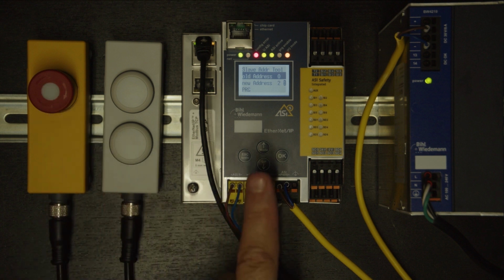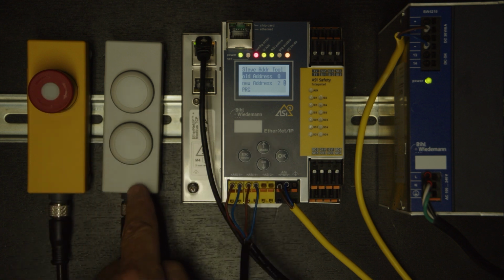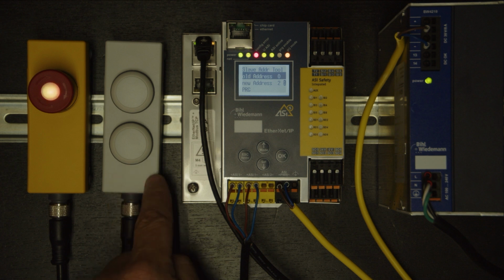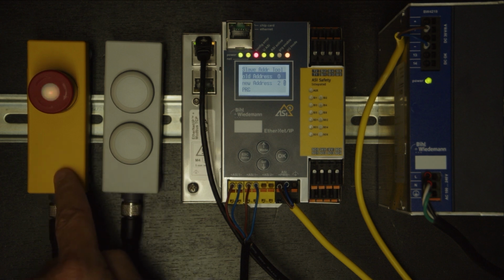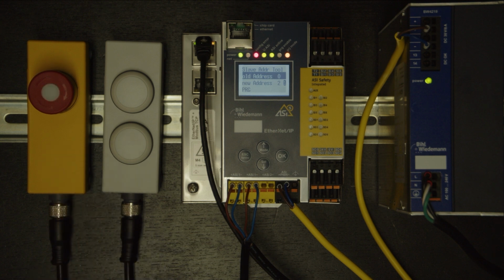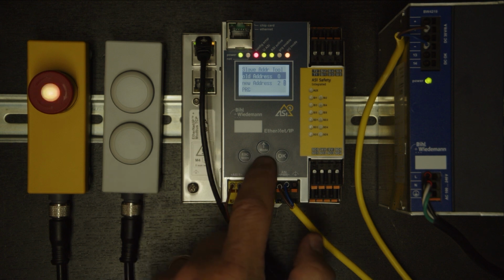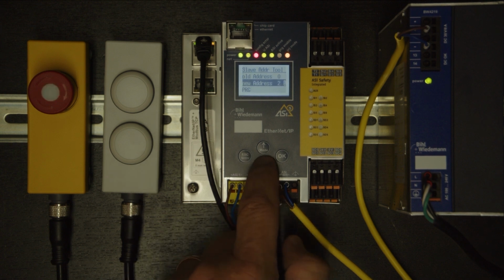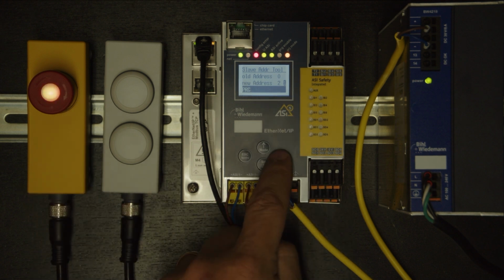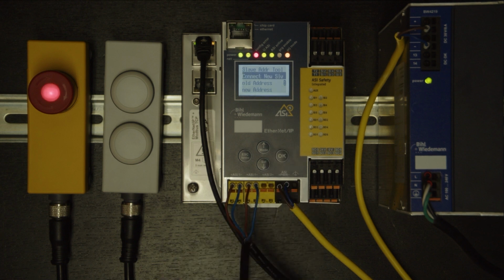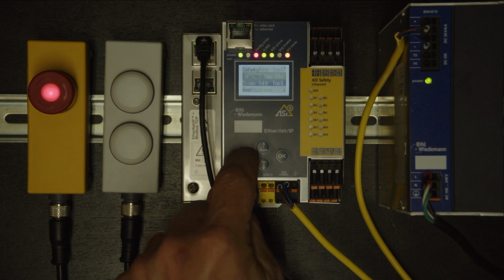Now, if you'll notice, this device doesn't take up an A and a B address. It only took up an A address. This device requires a full ASi address. Okay, so the first fully available ASi address is 2. All right, so that sounds good. Let's go ahead and leave it at 2. So the old address is 0 for this device. The new address is 2. I'll hit OK after I highlight program. It says OK. All right, now let's escape out.